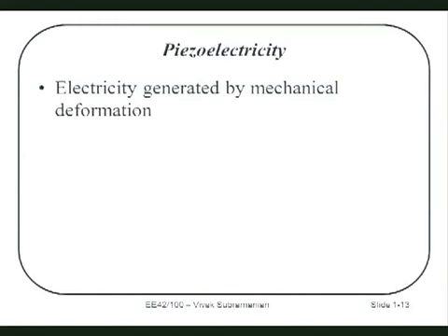Each time a drop is ejected from the inkjet printer, it's actually a piezo element. It's the reverse of this. Here, you generate electricity by deforming. In the inkjet systems, you apply electricity and then it deforms. And that pushes out a drop. Okay? So this is something that many of you probably own. I said HP does something different. Anybody know what HP does? How's the HP printer different from the Epson printer?